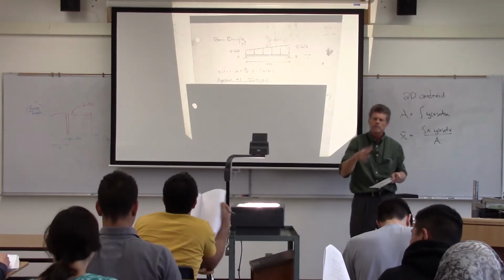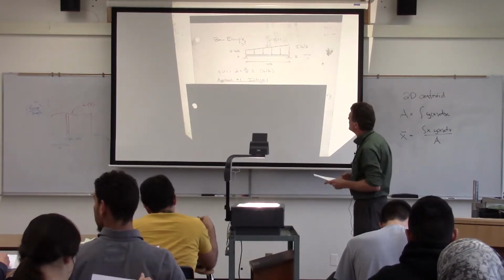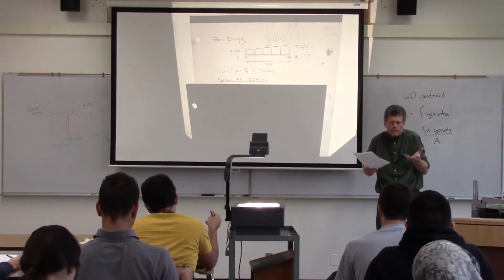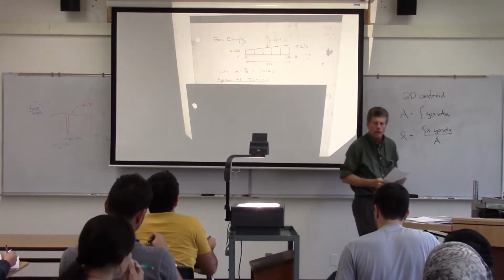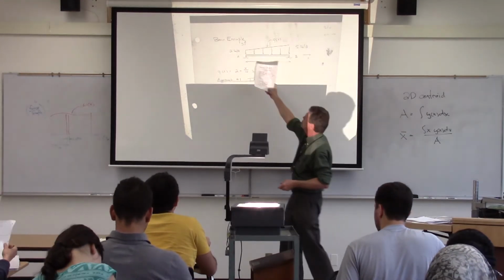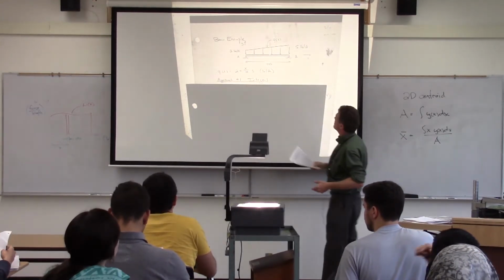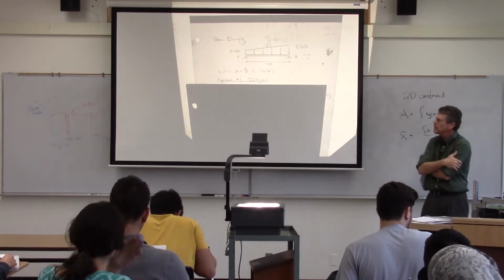And you've got most of it, but there'll be a few things that you're going to need to fill out along the way. Basically, we've been given a beam, and this is typical of a beam. This is what a beam's really designed for, carrying some sort of distributed load like so. So we've got a distributed load here. Basically, it starts at 2 pounds per foot and ends up at 5 pounds per foot across a 10-foot length from A to B.